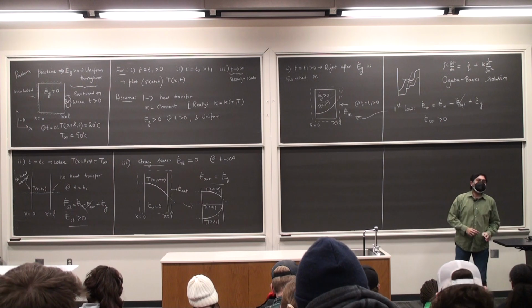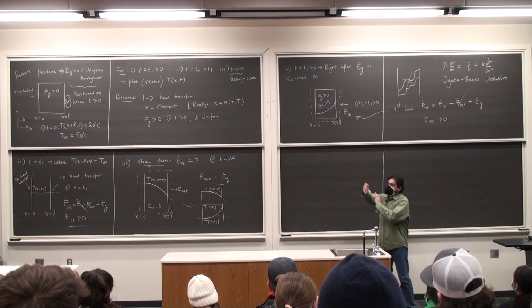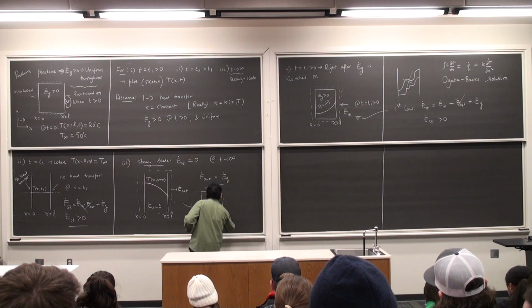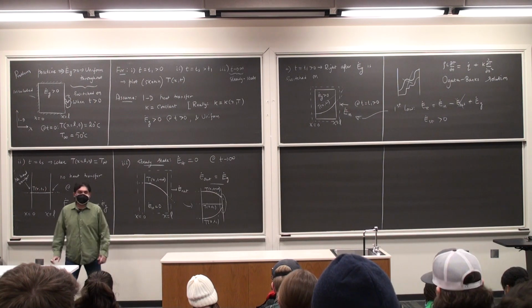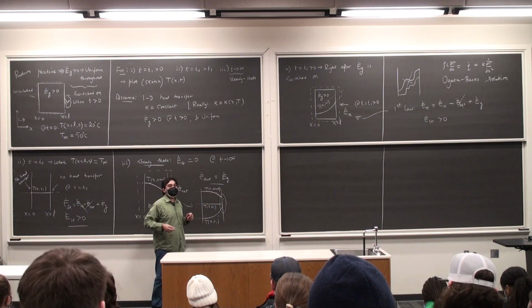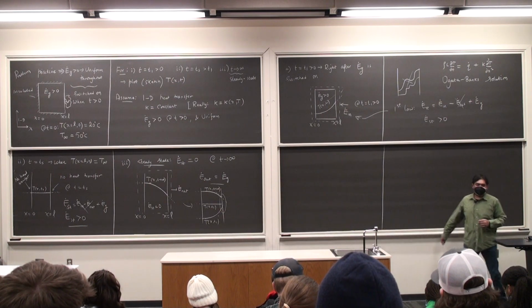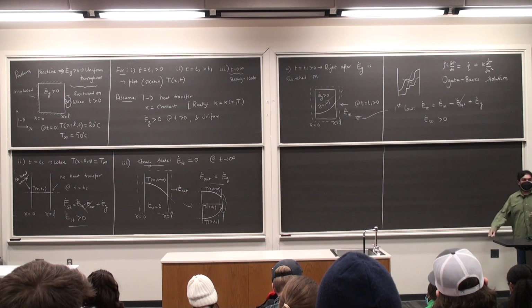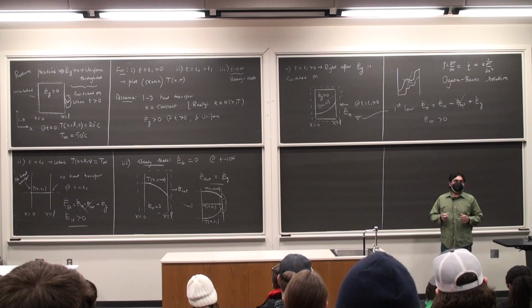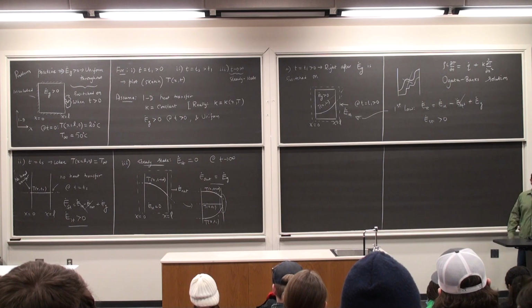Yes, question. So in the third case, will the surroundings be heated to more than 50 degrees Celsius? No, the surrounding temperature you assume is always like a bulk temperature. It is not going to change as much. You will see that there will be some wall effects which are taking place right there in the vicinity. But on an average, it's almost like taking a bucket of hot water and pouring it into the ocean. The ocean temperature doesn't change. So something similar to that. Or having a bucket of hot water close to the ocean. Alright. So which is why we call it a bulk temperature. But there is still heat transfer taking place. That cannot be changed.